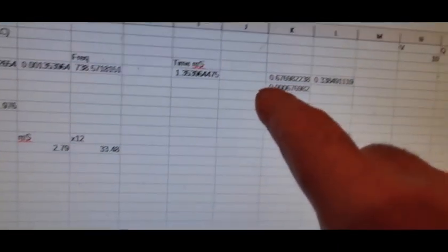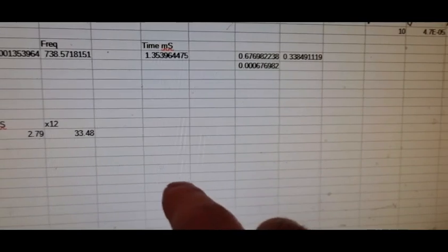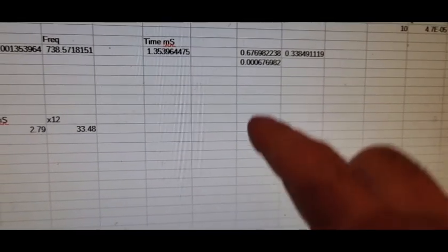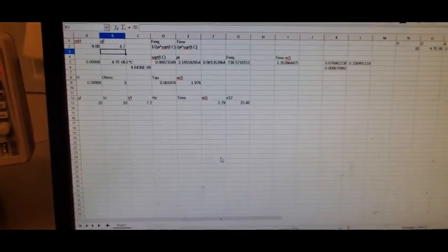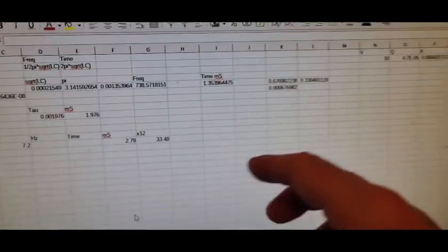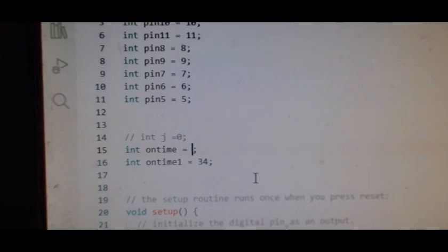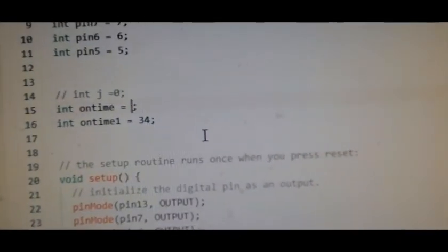So now it's going to go negative, it's going to go back to there, and then it's going to charge up. But the oscilloscope will measure for us the difference between the highest and the minimum. It'll give us the minimum voltage. That's all it's doing, is giving us the minimum voltage, Vmin. So you just make this longer, and then you know that you reached the minimum voltage. Instead of, when I was doing it here, sitting there fiddling around trying to find, well, is that the most minimum? Is that the most minimum? Now you just make it longer than the most minimum, and this thing will tell you for us. So I think it said 676. I'm going to make it 800.